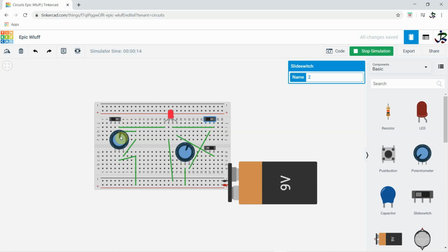So you can see the color combination, it's changing. See, the color combination is changing. At the end, this is the last color we can get with the help of this potentiometer. So this is how we can change the color with the potentiometer. I have shown you with 2 potentiometers, you will do with 3 potentiometers here. You will do an independent potentiometer for each LED. So for R this, for B this, and for green you have to add one more, and do the practical with 3 potentiometers to have different intensity at different points of the potentiometer.